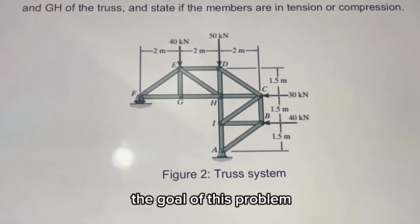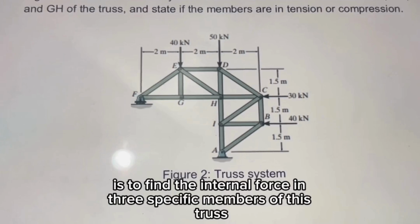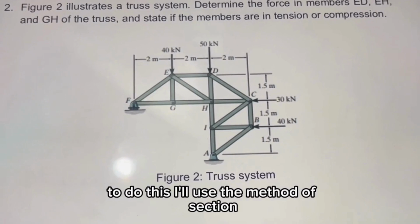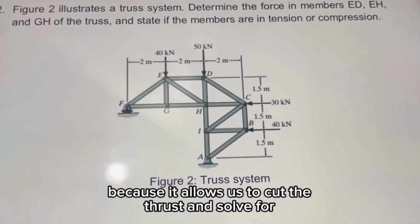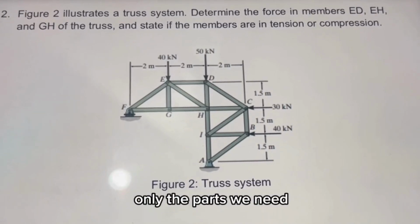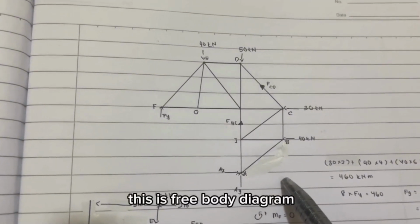The goal of this problem is to find the internal force in 3 specific members of this truss, which is ED, EH and GH. To do this, I will use the method of sections because it allows us to cut the truss and solve for only the parts we need. This is the free body diagram.